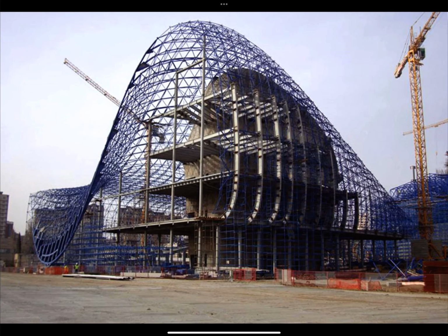And here you see another image of that project under construction. So you can see here that there is a site cast concrete core. Then there is a steel frame made of W sections built around that core, and some of the W sections are curved in profile. And then the steel space frame obviously defines an outer envelope for the building.